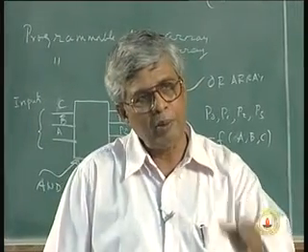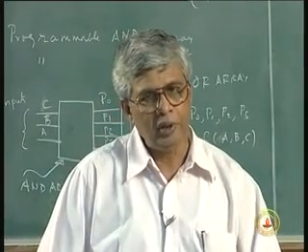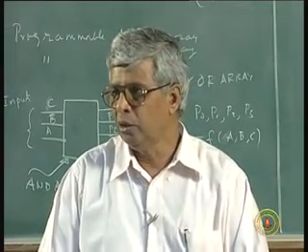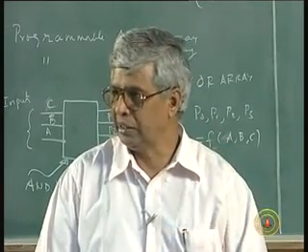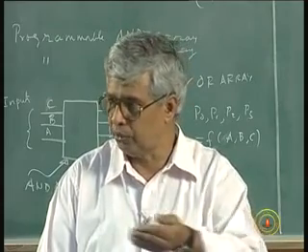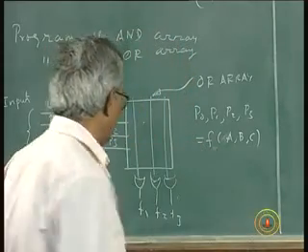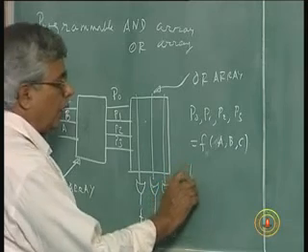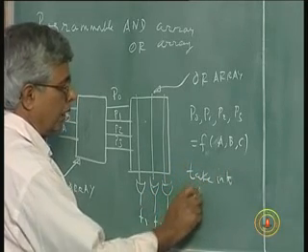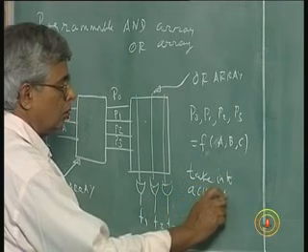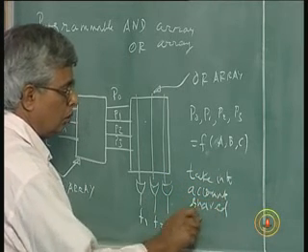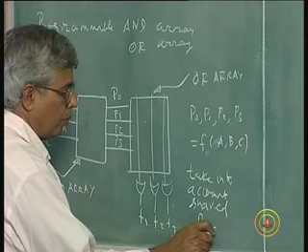At the same time I will keep in mind, is it possible to have the same product terms appear in more than one output function, which means I can share the product terms in different outputs. So also take into account shared product terms.